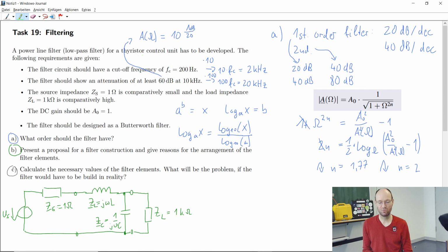the motor control unit. But the price that you need to pay is, of course, the power electronics you create will then create disturbances at higher frequencies. But for these higher frequency components, okay, then we can use a linear filter or we can use this passive filter. But if the cutoff frequency is then not 200 Hertz, but let's say 20 kilohertz, something like this, then L and C must be much smaller. So no problem with this.